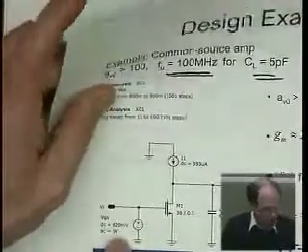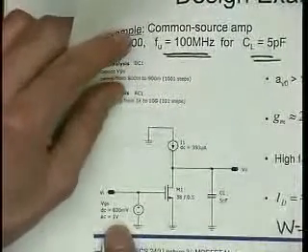In small signal, everything is totally proportional. So it doesn't matter. I could test my circuit with 1,000 volts, and then the output would just be 100,000 volts. The circuit is linear as soon as we go to an AC analysis. So I really can use 1 volt just as well as I can use 1 microvolt.